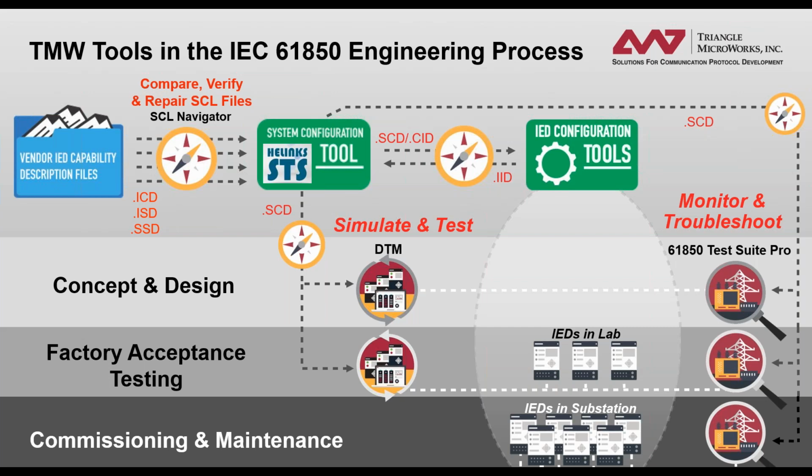So in that case, yes, I need to reload the devices that are subscribing to this GOOSE control block. But there may be other changes that I do on a device that don't affect any other devices. So that's still the responsibility of the system designer to know what he is doing and to know, if he does a change, what other IEDs are affected by that change, because they somehow depend on that change.